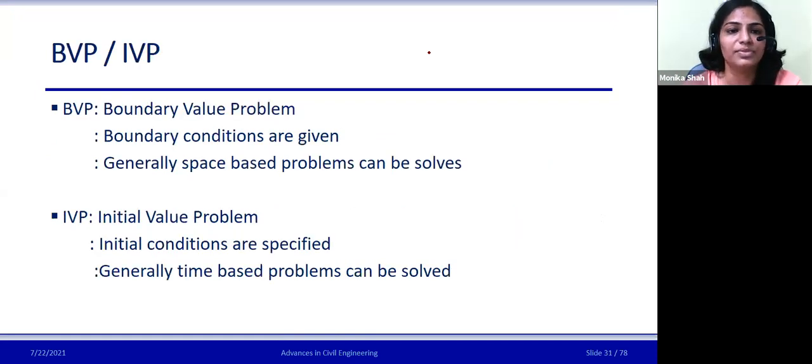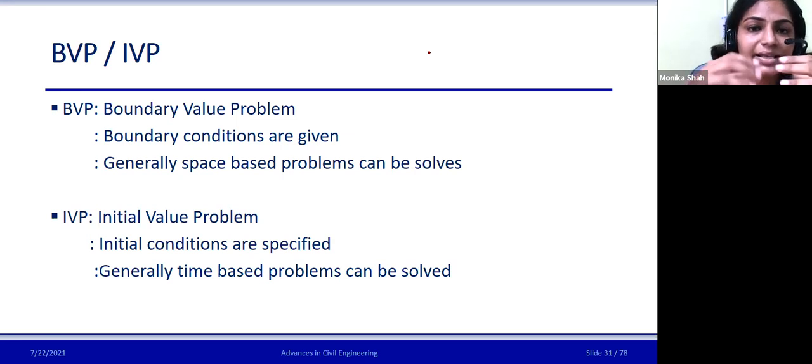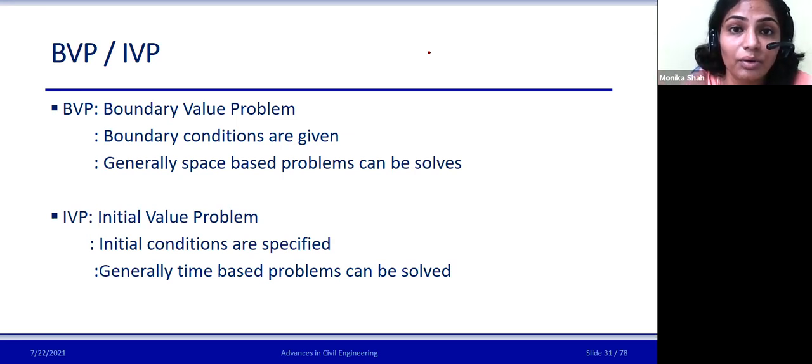There are problems where we have boundary conditions. That means the atmospheric conditions we have to implement. The walls, suppose my liquid is flowing through a pipeline, right? If it is pipeline flow, in that case I have to select the boundary layer effect. In that boundary layer effect, I have to put the velocities as 0 at the boundaries. That would be my boundary condition. I have to put it. That is the rule. We have studied the boundary layer theories, right?